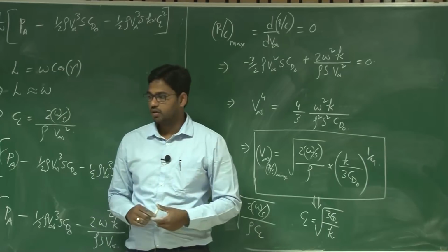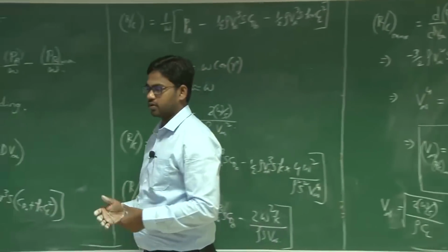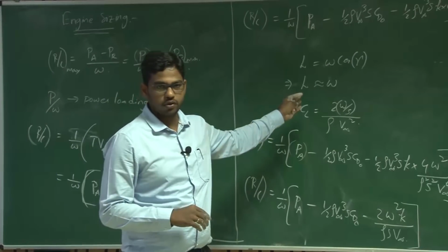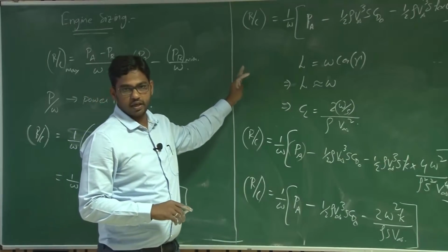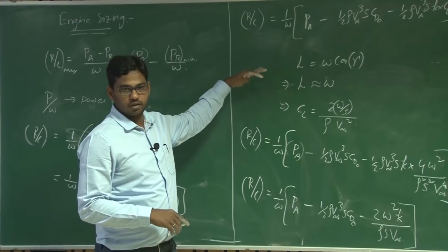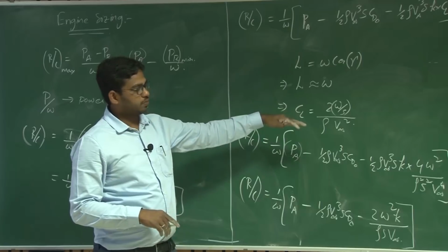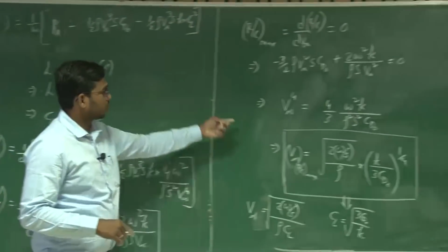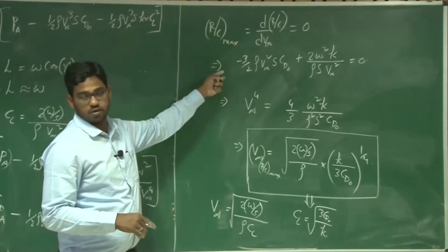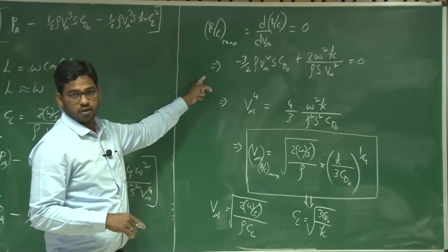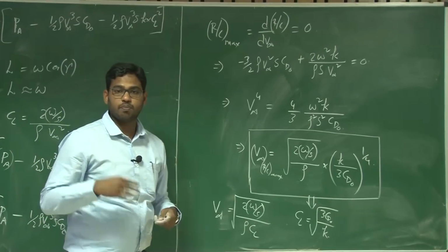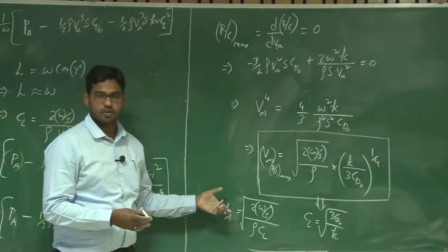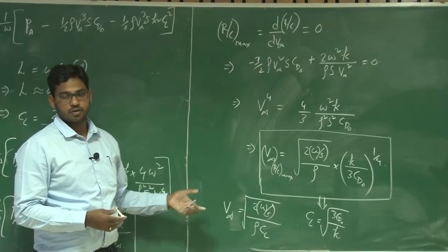Now, let us see how you select a power plant based upon this. We have two parameters right now. In the case of small UAVs, cruise and climb are the major phases of flight, right. You need to know the maximum power requirement in cruise. At the same time, we should also get to know what power should be supplied to the system from the power plant for various climb rates.